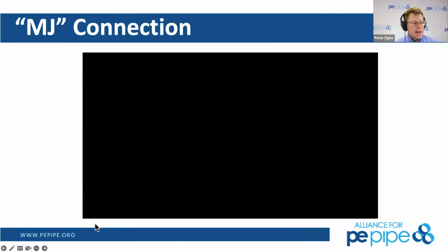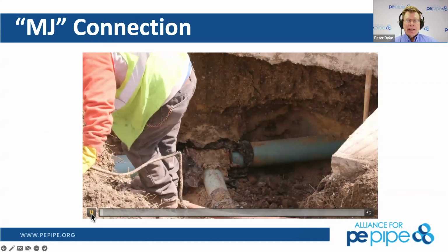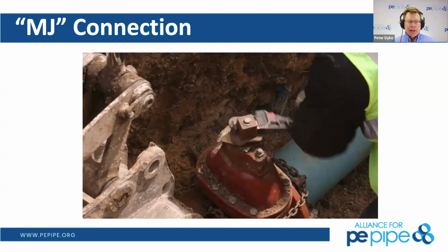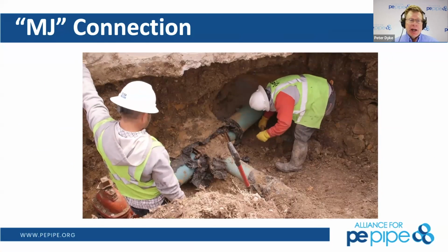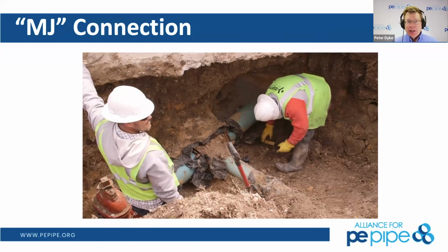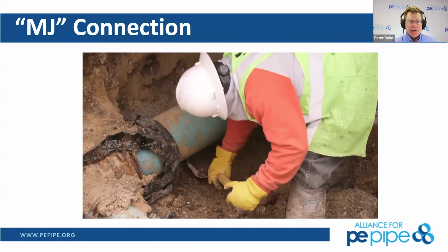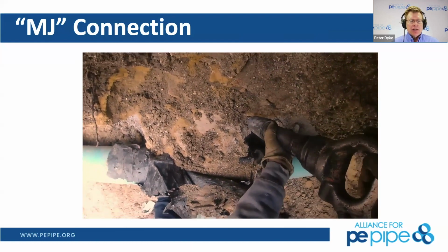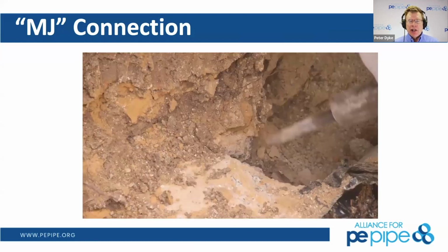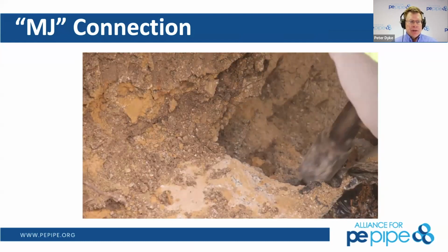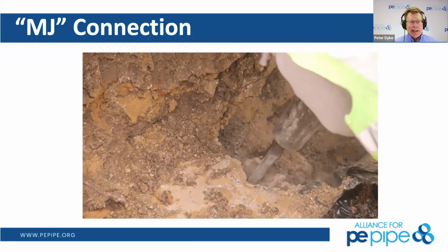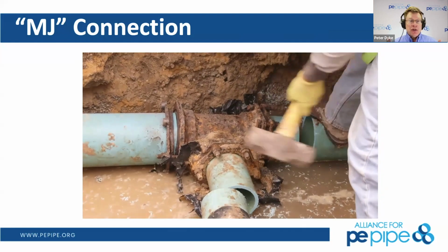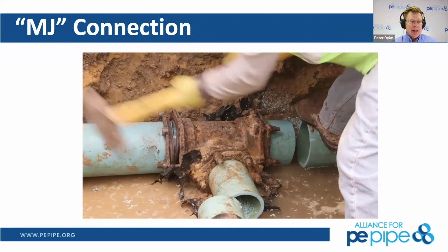So Dusty, here's a video that, thanks to Dan Landy, is our most popular video on YouTube. This is a demonstration of putting in a polyethylene spool piece to connect to an existing PVC line. And you see here the crew, Dusty, is working on getting the concrete out because there was a change in direction. So we're going to replace that T with a new ductile iron T after we get through with the concrete. While this guy's doing that, there's a guy at grade building his polyethylene spool piece, getting it ready, Dusty, with 2 MJ adapters that we'll see momentarily.